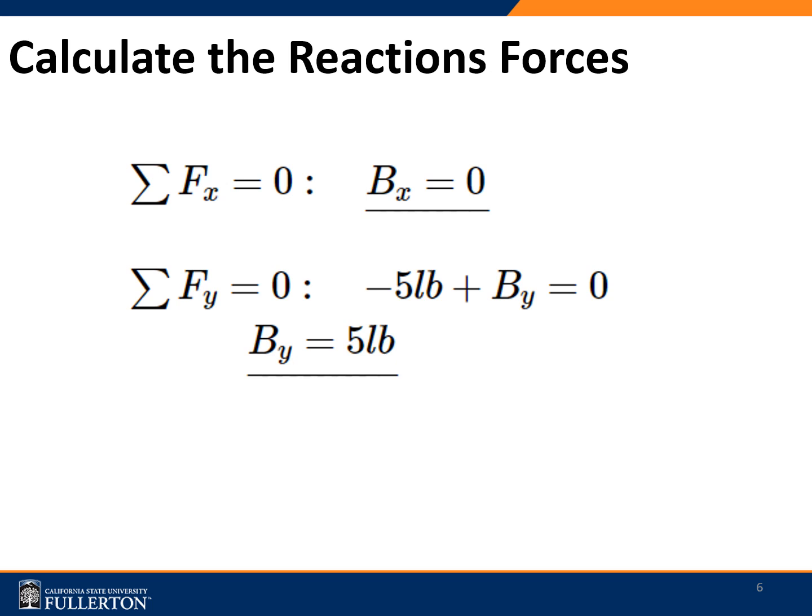Then compute the reaction forces at the support. Since the support at B is fixed in this example, there will be 3 reactions at the support, namely B sub y, B sub x, and M sub b, which is the moment. Applying the conditions of equilibrium, we get the equilibrium equations as shown here.